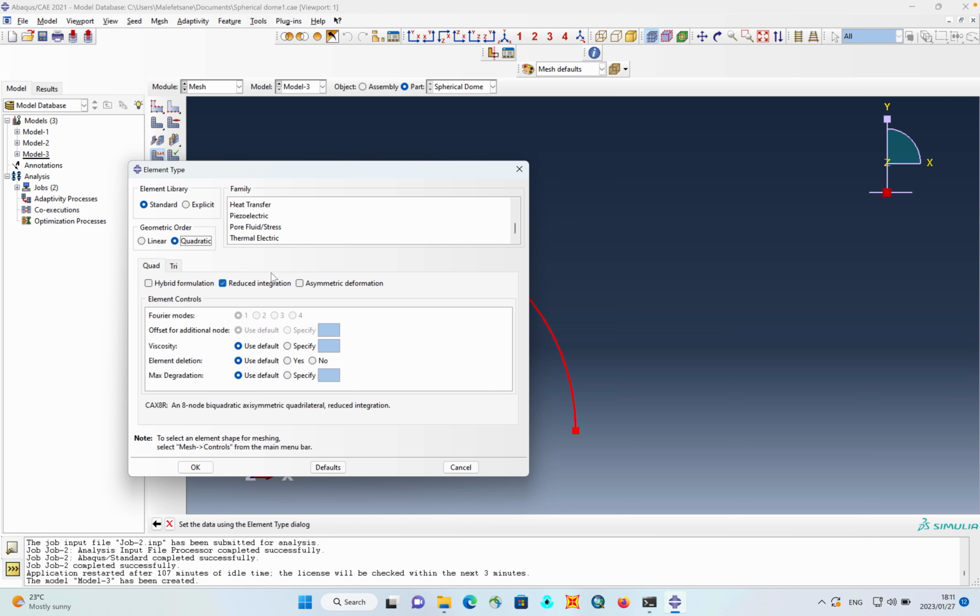And then we're using reduced integration. Reduced integration basically means your element has one Gaussian coordinate if it's a square element. So you're reducing the time it takes to run to the solution as well. It's all about that time effect, because believe me, when you're solving a huge problem, the computational time could take a while, and you may find out it even crashes. So sometimes you don't even have to do mesh convergence, and that's when you have to resize your element size, and imagine now you're going to have to wait.